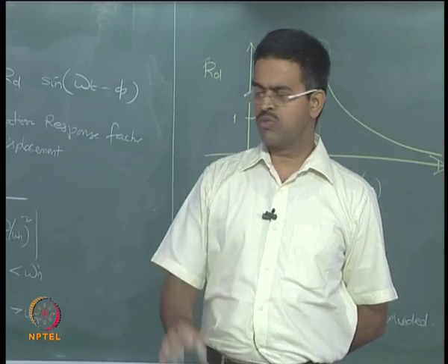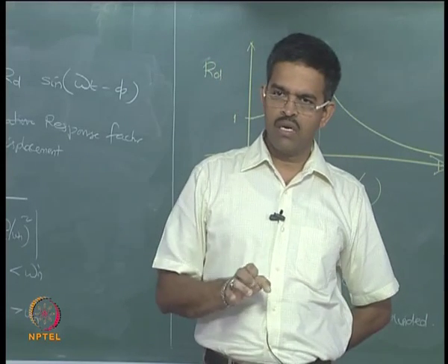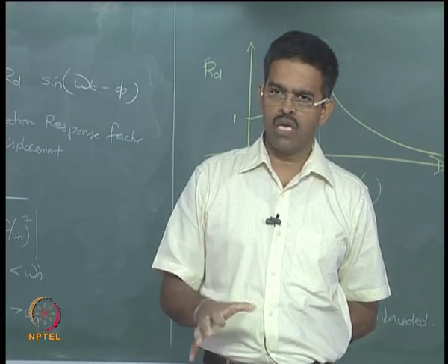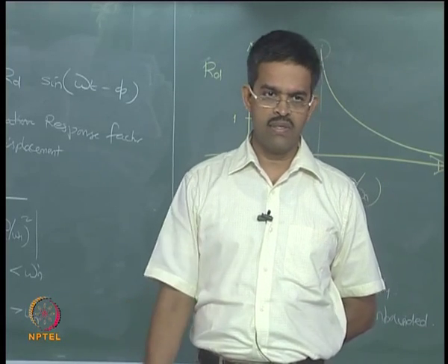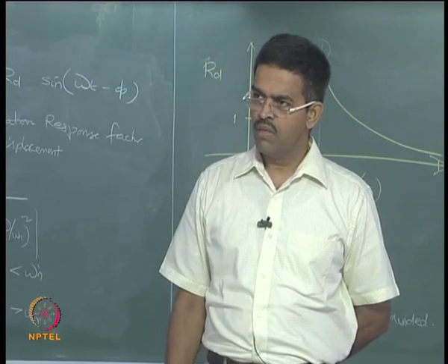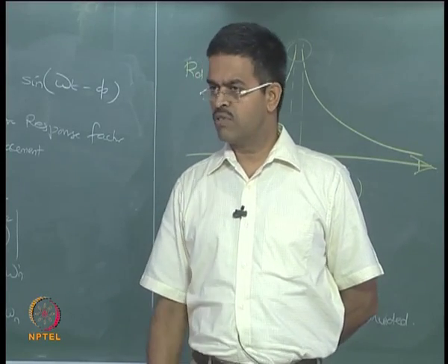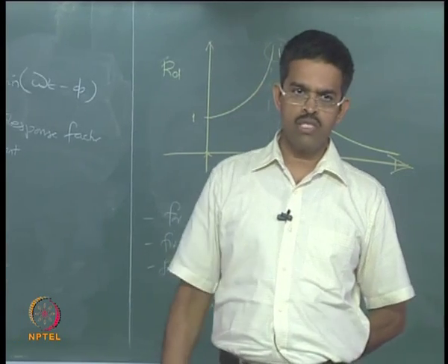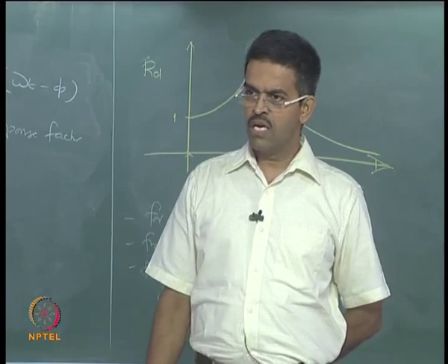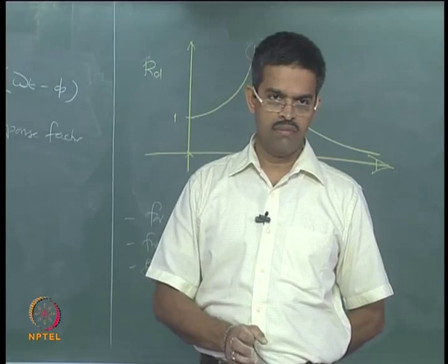But here we have taken a simple case to identify clearly the window where we are interested. We have also had a question: why is steady state always considered to be important in dynamic analysis vis-a-vis transient response? Because transient response is dependent on the initial conditions of the problem, it may decay, it may die down, it may become insignificant in comparison to the steady state response, because steady state response is always a function of forcing frequency. Because we are talking about force vibration, it will be present. Therefore, steady state will always exist, transient response may or may not be significantly there compared to steady state.